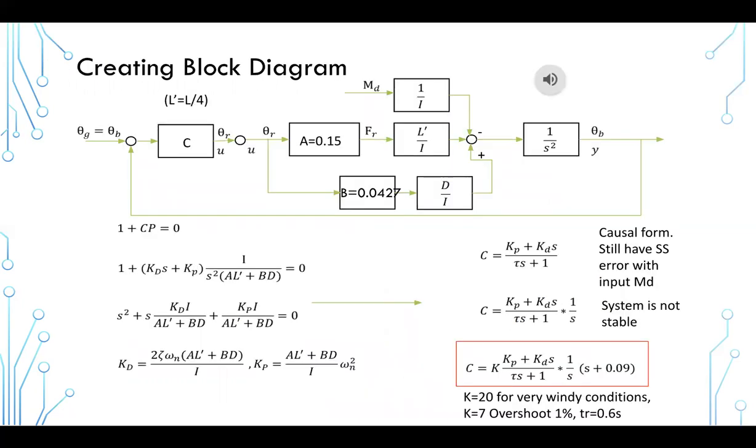A PD controller was designed as shown in the slide. This was done to have a general idea of where the poles and zeros could be placed to achieve a small overshoot and rise time. A PID was then designed using the root locus method to change the gain, poles, and zeros locations. This was done to eliminate error due to disturbances.